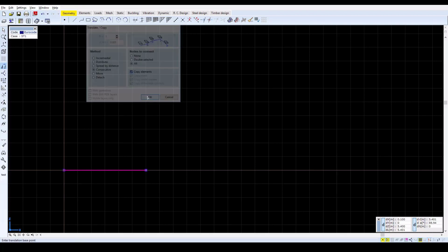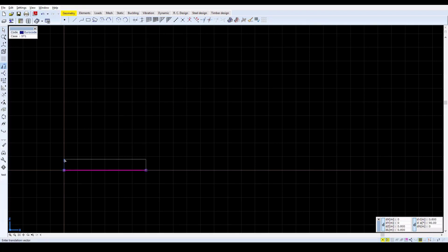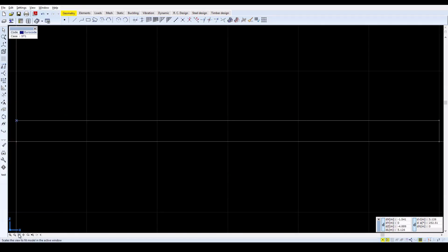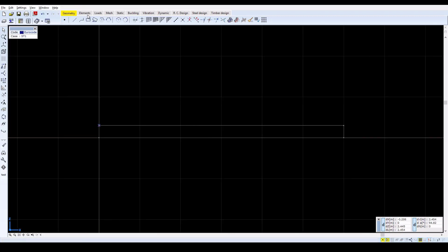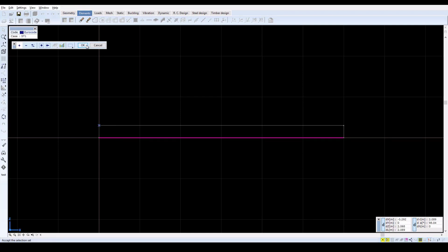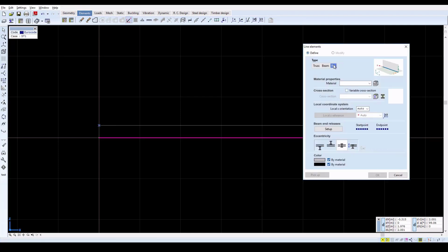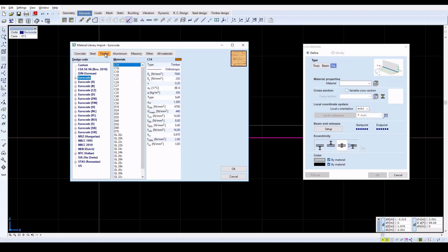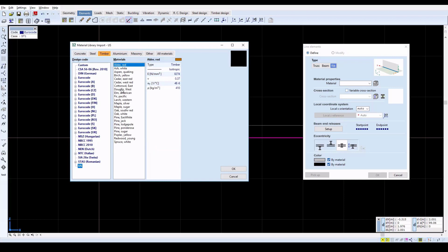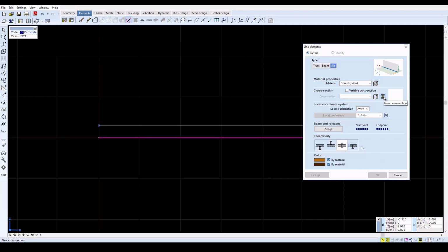The composite member consists of two wood layers interconnected by multiple connectors or an adhesive that provides interlayer force transfer. Each layer has to be modeled separately along their own axis using rib finite elements. The bottom layer has a 20 by 40 centimeter cross section and the top layer is 20 by 20 centimeters, both made up of Douglas fir timber.